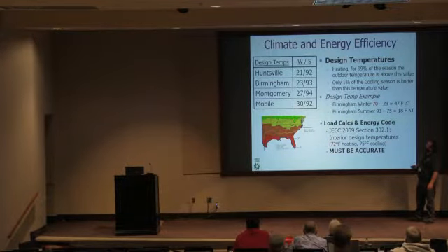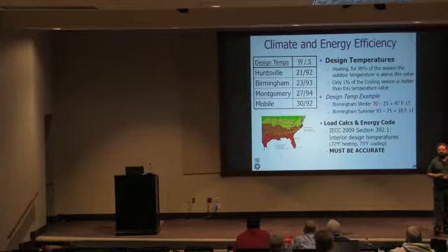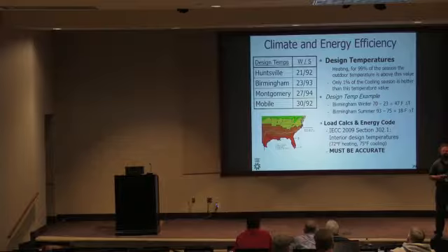All right. Will this impact your question? When it comes time, when you're replacing the roof, you find a piece of roof decking, let's say a 4x8 panel, that needs to be replaced because of rot or for various reasons, past leaking. What happens to the spray foam that's stuck to the bottom of that? I would basically cut the foam out, remove the decking, replace the decking, spray another pass of foam. So you have to call you back out, set up and spray it back on.